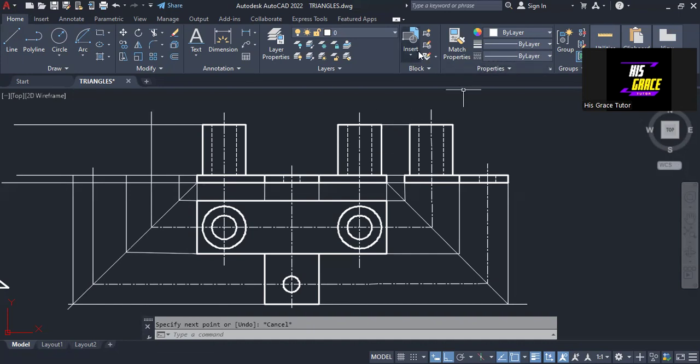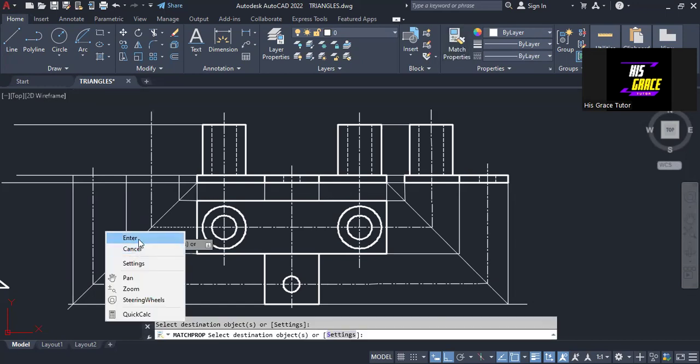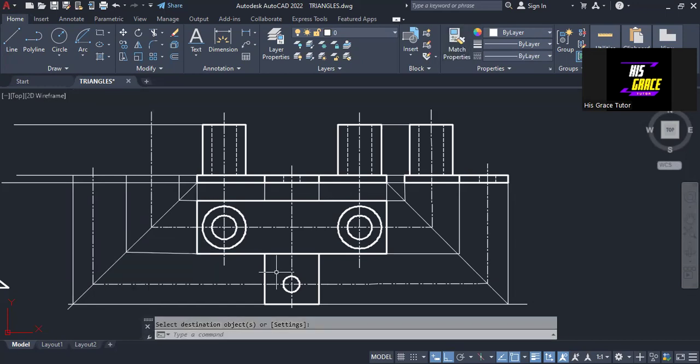All right, so I'm going to mesh the center lines. So I will click on Mesh. So select this and then select this line and this line. All right, so we have this now. So what I'm to do now is to bring out the end elevation. This is the right end elevation. We are going to have it here.